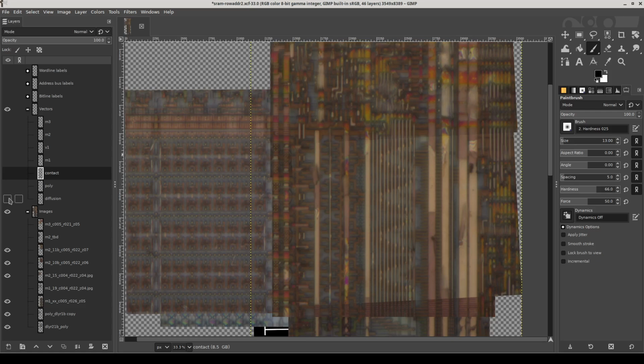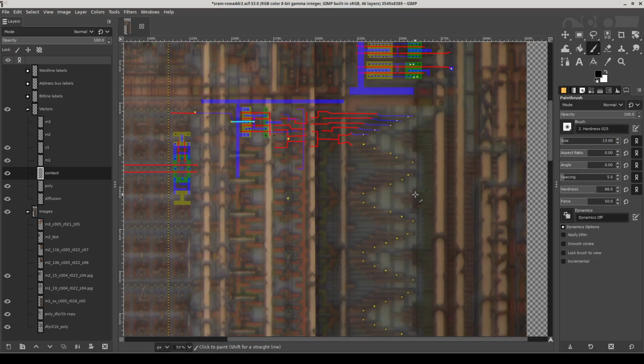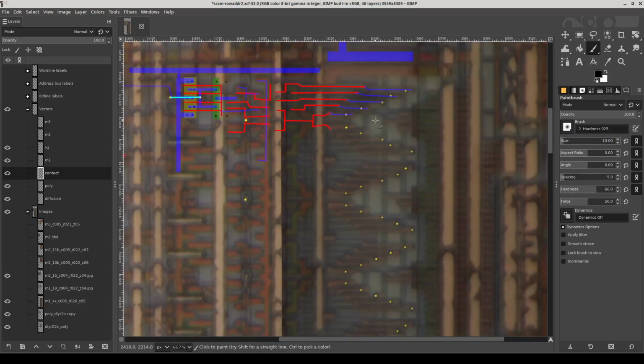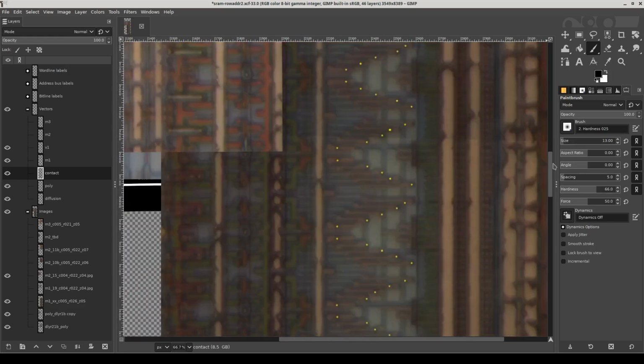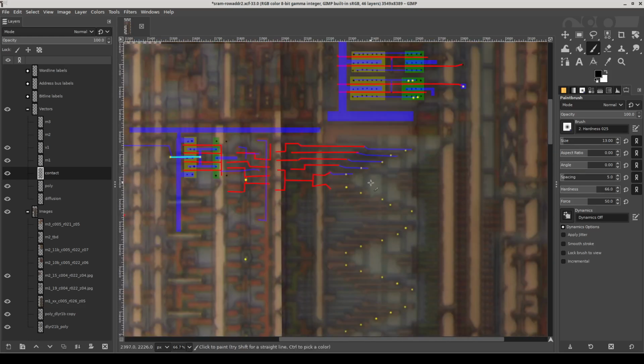So I'm going to turn on the tracings since some of those are a little bit hard to follow, especially the via 2 layer. And we're going to go back to this image because the contrast against the yellow color I used for the vias is a little bit better. And so it's pretty clear that we've got a similar but not identical pattern here. But every row has exactly 5 vias, which is interesting because we have 32 rows. That is consistent with these somehow being related to address bits. But of course, how do we know which row is which?